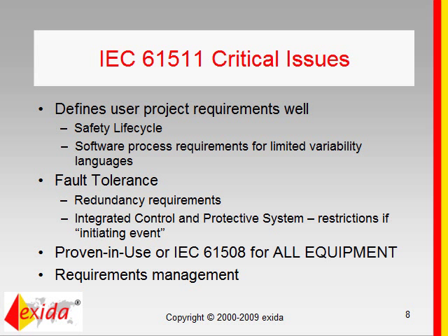Some critical issues in 61511. It defines user project requirements very well, and talks about the safety life cycle. It addresses the software development process for limited variability languages, the requirements that you need to meet. Limited variability languages are languages like function blocks, structured text, sequential function charts, ladder logic, basically the IEC 61131-3 languages, if I remember correctly.